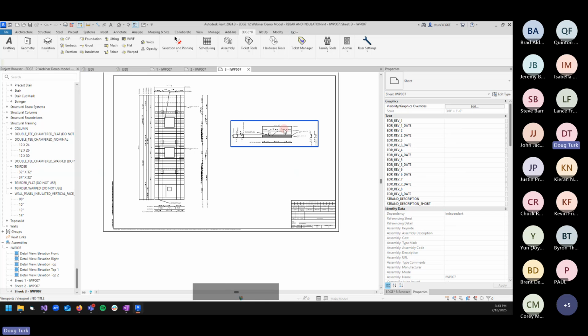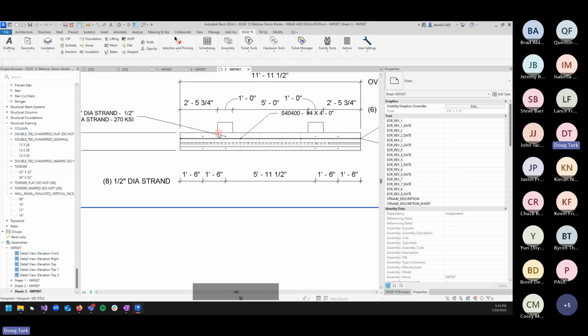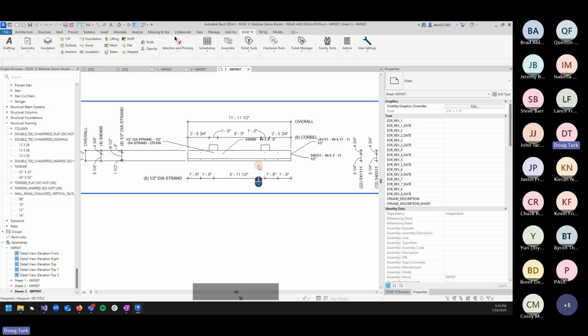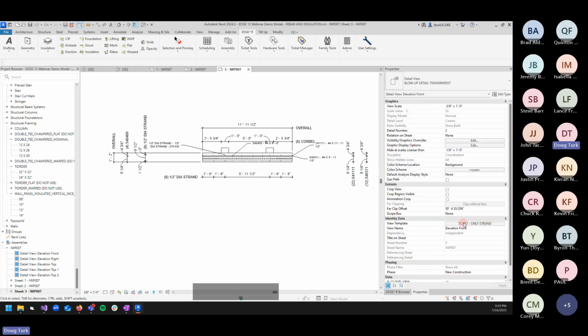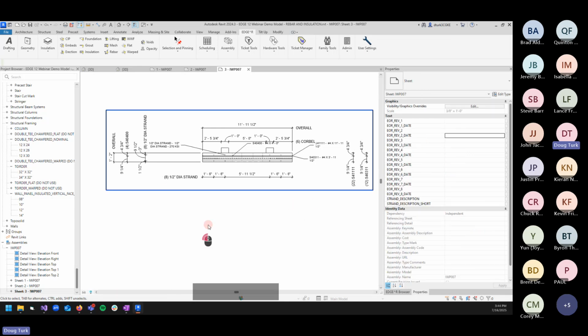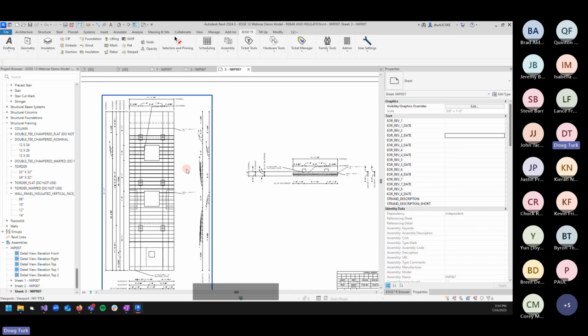So that shows this. Again, you can see the strand from the top view here. You can also see the straight bars. This is just showing some of the different kinds of views we can generate with regards to all of that. The way that we're showing different things is via view templates set up through Revit. You can customize those with all of the features present in out-of-the-box Revit, and our ticket templating system will actually save that view template information to the ticket template as well. So all of that's set up ahead of time.